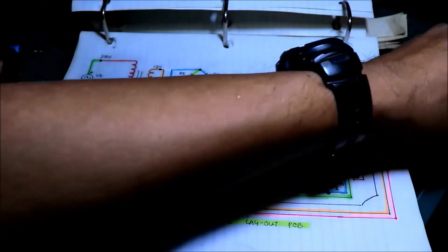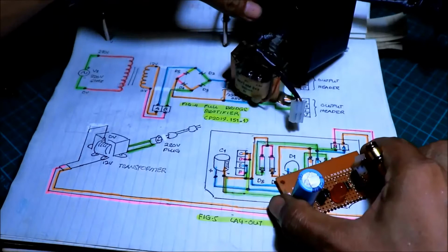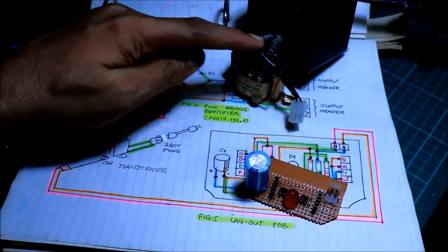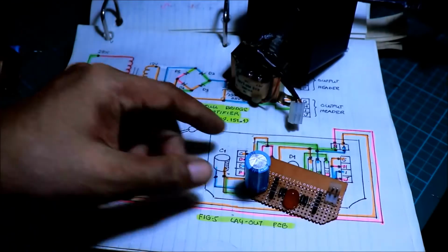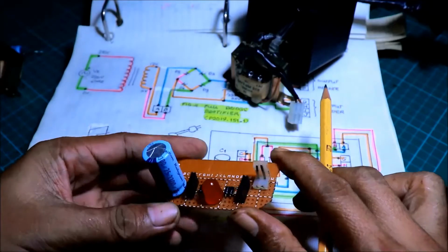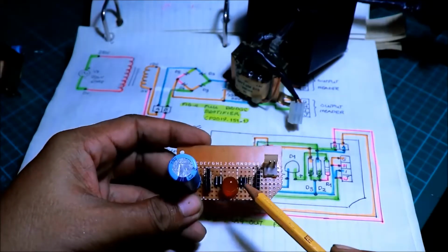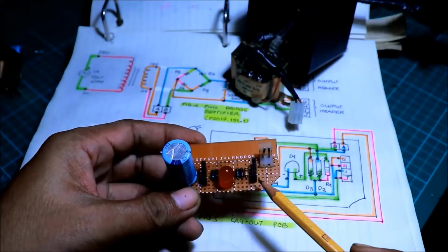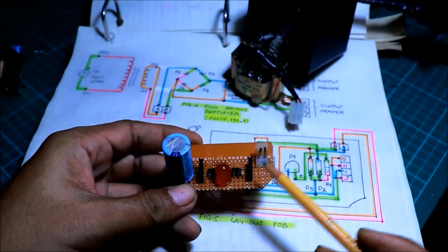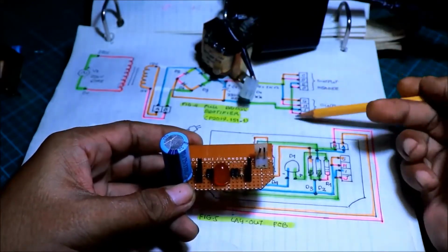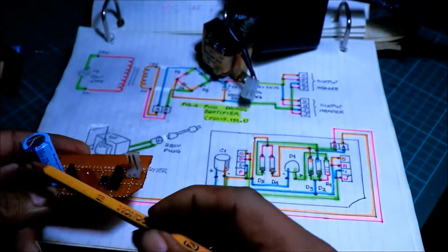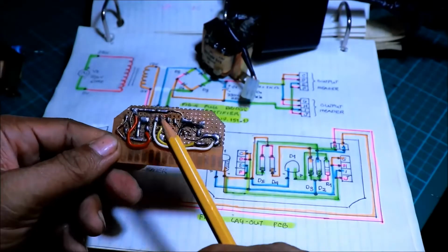And this is now the final product. This is the transformer, the secondary, and then this is now my full wave rectifier: 4 diodes, 1 LED, 1 resistor of 1 kilo ohm, 2 headers, the header of the transformer, capacitor, perf board, some jump wires.